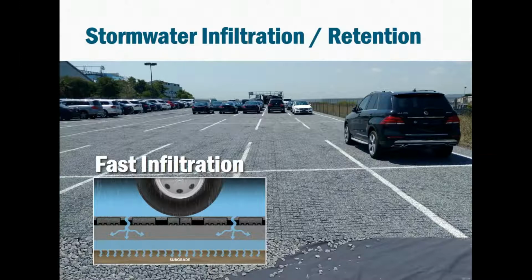And in the GeoBlock units, the loose and protected topsoil allows water to infiltrate faster than a typical vegetated area on site. Both GeoBlock and GeoPave systems offer significant storage of stormwater in the cross-section as it moves into the groundwater system. Because the water infiltrates through the system, there is minimal sheet runoff at the surface, reducing flooding potential on and around the pavement.